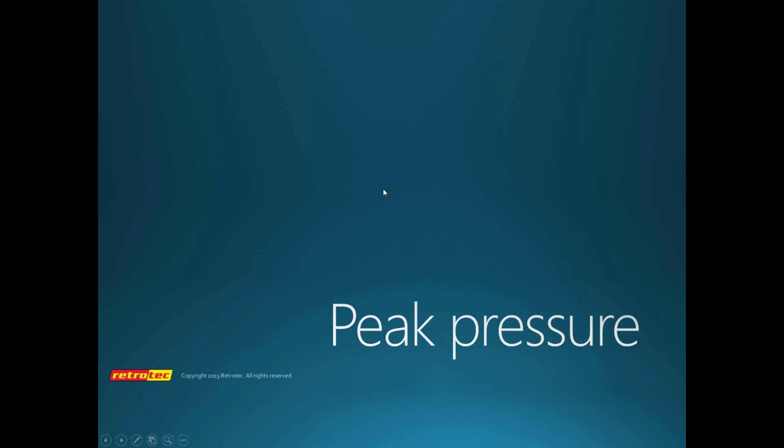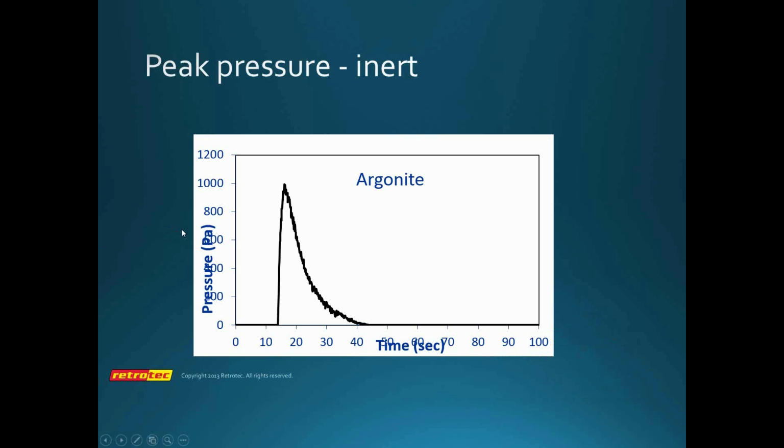First topic we're going to get into is peak pressure. And peak pressure is the big change that's occurred in the 2012 version of NFPA. Actually, the requirements for peak pressure evaluation came out in 2008, but the standard was a bit of a jumbled mess, and I don't think anybody could make heads or tails of it. So we look at the 2012 version as the official one that says, yes, you've got to start doing a peak pressure evaluation. So that's what we're going to start talking about a little bit today.